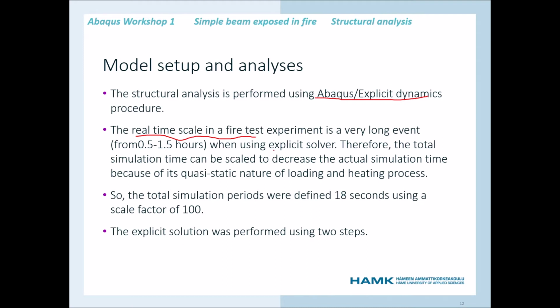So when we are using this explicit solver, we cannot run these long simulations. Therefore, the simulation time can be scaled down from the actual simulation time because of its quasi-static nature of loading and heating process. So it doesn't affect. So we reduce the total simulation time by a scale of 100.